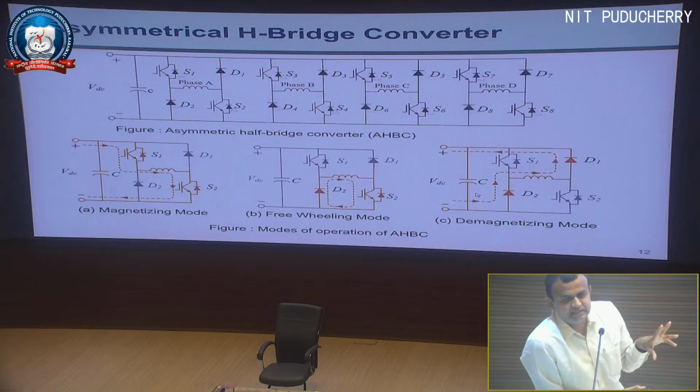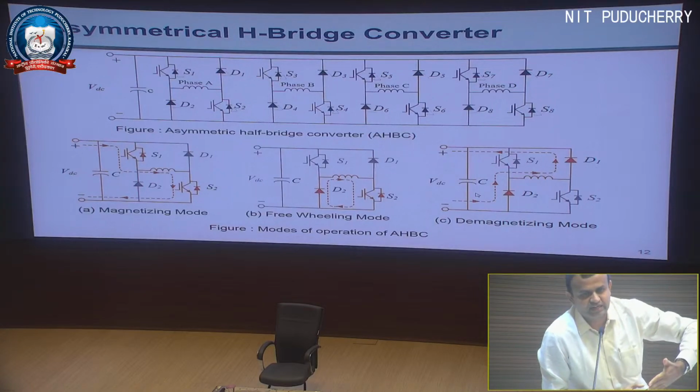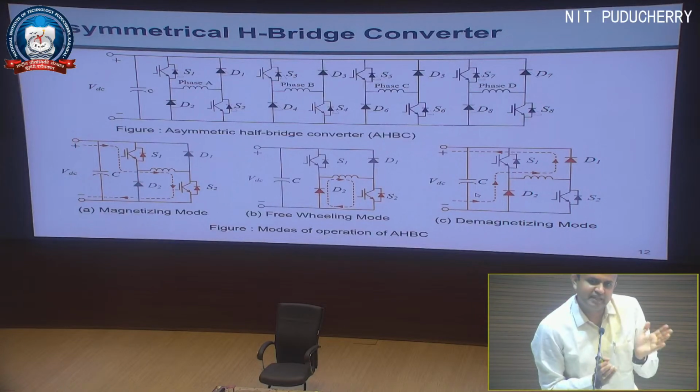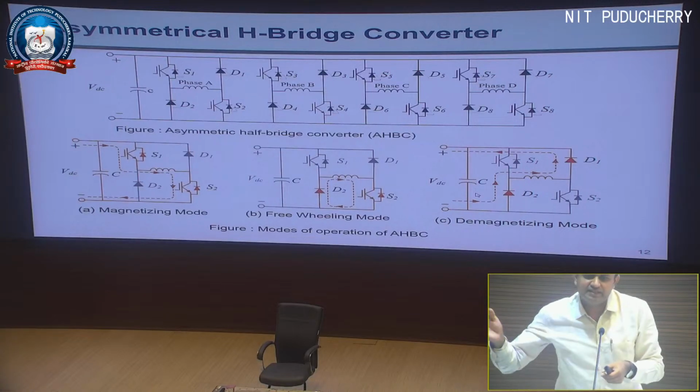But the difference is in the MOSFET, if you see the layers, like a PN layer, PN layer. Have you heard about the inherent nature? If you cut the semiconductor and analyze it, you can find that an inherent BJT, an inherent diode will be present, because that happens naturally. Basically, what is the diode? If you connect a P and N layer, you will get a diode. The rest is like addition.